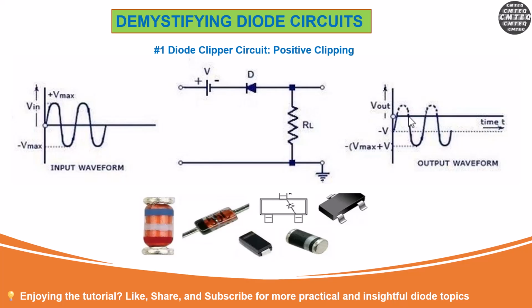Now from here, we are starting to go into the negative cycle. The input voltage is going to start to decrease to the negative, and it is going to be less than this voltage here. So at this point, the diode is going to become reverse biased. Because the diode is in reverse bias and the input is a negative voltage, the output will follow the input. That is why you get this output here that follows the input.